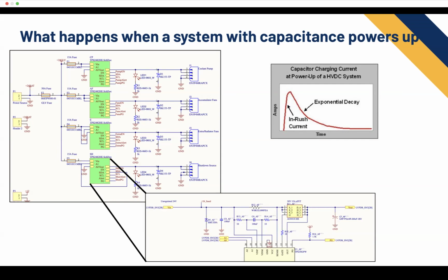That's going to be like 1,340 microfarads, somewhere around there. That's a lot. And that's enough to pull an insane amount of current. And when we pull that much current, remember what we have at the beginning, we have these fuses. And that's definitely going to pull more than 15 amps. So how do we stop this fuse from burning and still turn on the system?